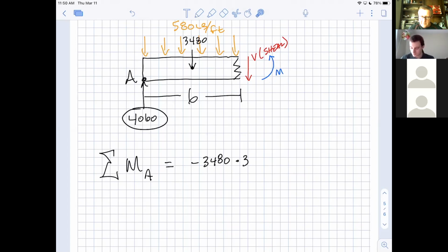Now, didn't we already do this? Let's think about this for a second. If I told you this beam was welded to the wall right here, didn't we say because that was a fixed connection that provides vertical support, it provides horizontal support and moment support? In other words, we added those earlier. Well, isn't this fixed? Isn't that connected to something? It's no different. It's connected to something. So of course it's got shear and moment. It's got vertical resistance. And by the way, it even has horizontal resistance because the beam's not going to pull apart. We just don't have to calc that right now.